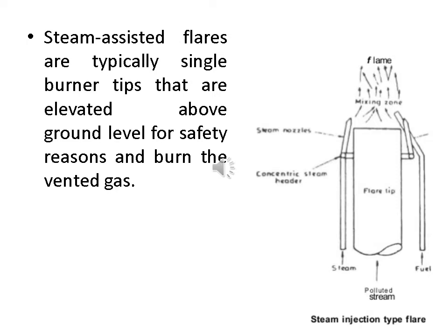Mainly these steam injection flares have a single burner, and for safety reasons we use elevated towers. Most commonly this type of flare is used in chemical industries and petrochemical industries. In that way we can reduce hazardous situations.